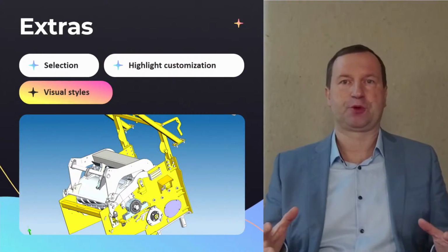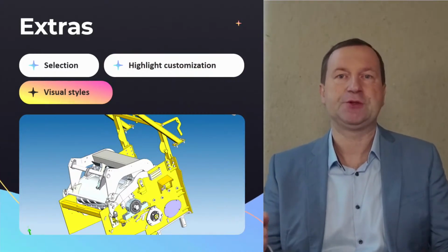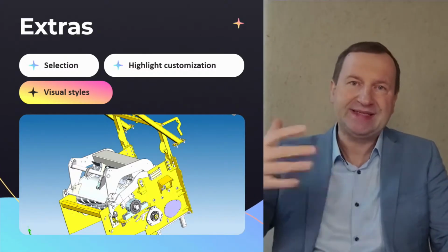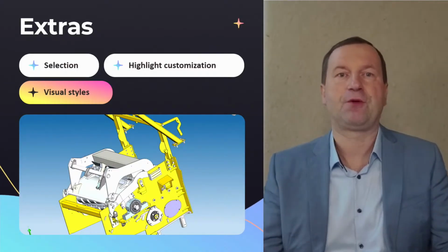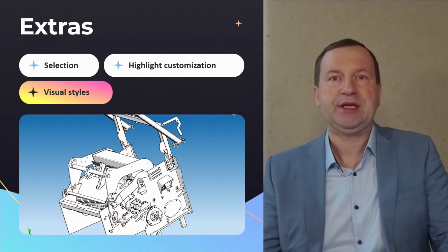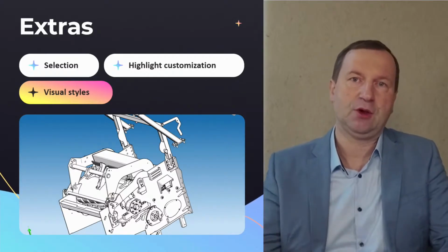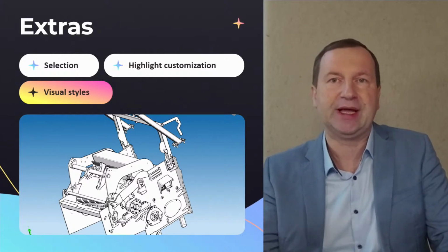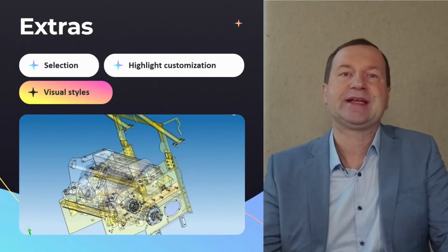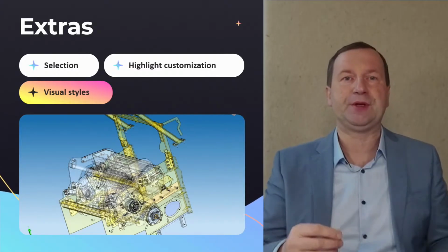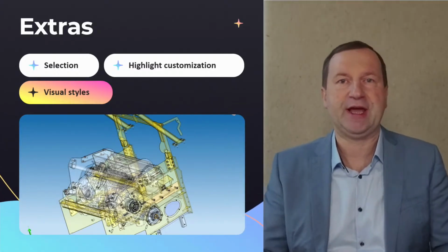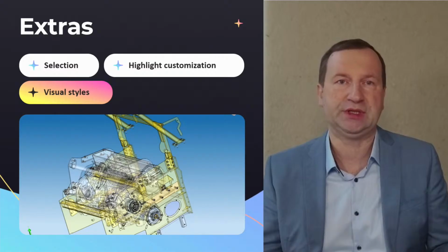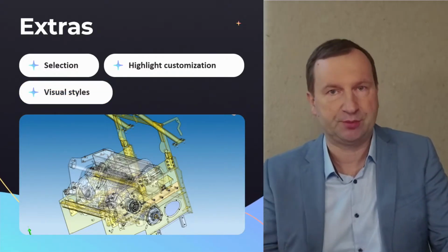Another notable feature provided by Visualize SDK is visual styles. Visual styles allow for impressive visual representation, even for relatively simple models. Adjusting a few visual style options such as edge mode, edge crease angle, and face transparency can significantly improve rendering effects in the final model representation. In some cases, this approach is more convenient and faster than adjusting material properties.